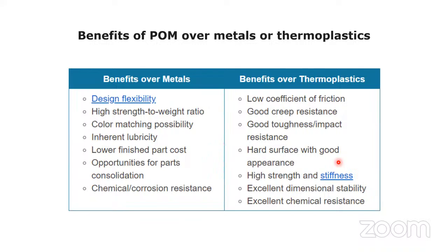Sir, there is one more thing, no? In this material, laser welding is possible. In other materials, if you consider PP, polypropylene, in automotive applications to connect two parts, they generally use a thermal process.